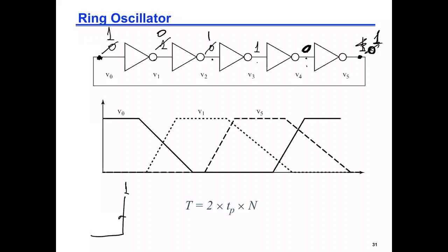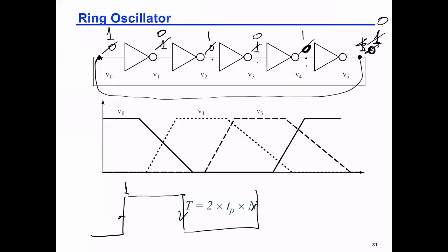The zero will flip to 1, the 1 will flip to 0, the zero will flip to 1, in a cycle. The ripple effect is effective immediately. So for us, the fall or the rise, this switching is because of the short, it is effective immediately, but for this location to flip I needed to have a rippled or domino effect through all the 4 transistors, the inverters, 5 inverters, right?